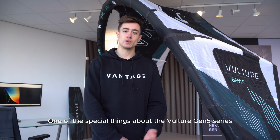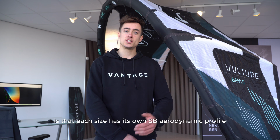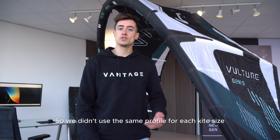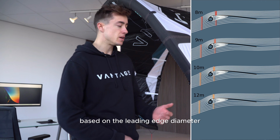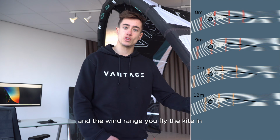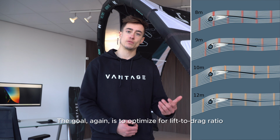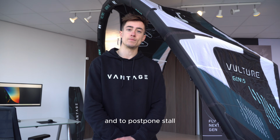One of the special things about the Vulture Gen5 series is that each kite has its own SB aerodynamic profile. So we didn't use the same profile for each kite size, but we optimized it individually based on the leading edge diameter and the wind range you fly the kite in. The goal? Again, to optimize for lift over drag ratio and to postpone stall.